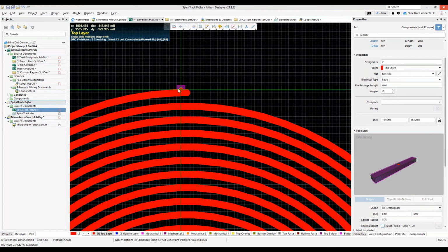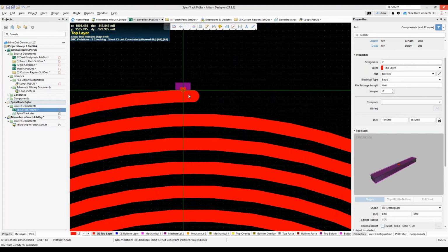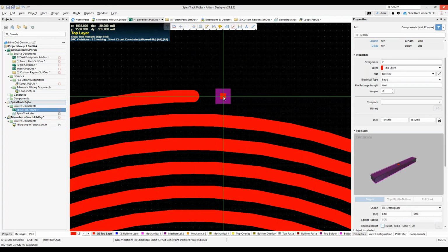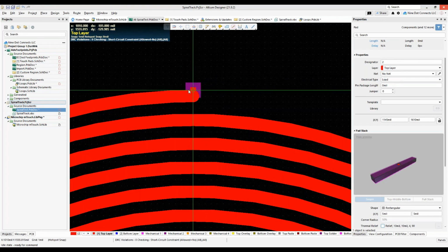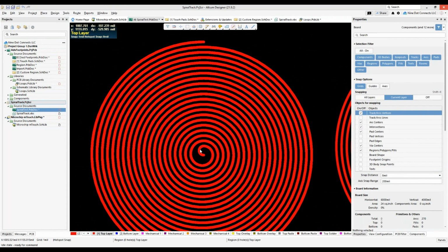And then from there, I would have to go in there and I would drop this in. Of course, I've got to change my grid to something really small. And even this one's not pushing in there. So I'd have to either suspend the grid or something to do it. But the point is I would need to get this in there. And probably the better thing for me to do is just to have done this on Mechanical 3 to start with. But that's the idea behind it. Okay, but make sure you put a pad here and a pad at the end when you're ultimately doing this.